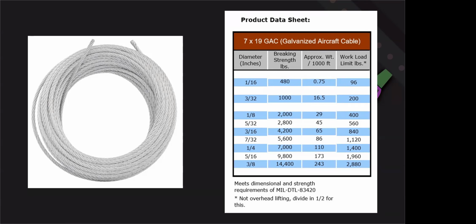We're not holding people up, so you probably don't need to be quite that low. But this is where the factors of safety come in, and they know what they're talking about with these. So if you're worried that you're going to have a lot of load, look at this working load, and make sure that you're in a reasonable proximity to that. Definitely never above your breaking strength, because that's when the thing will actually break.